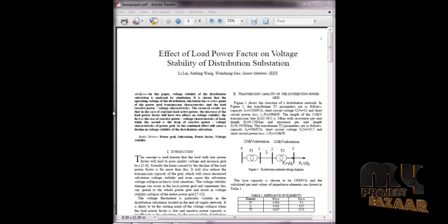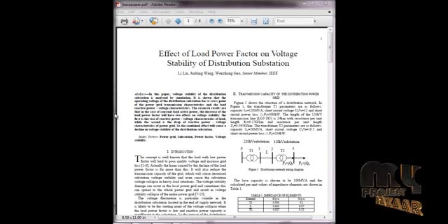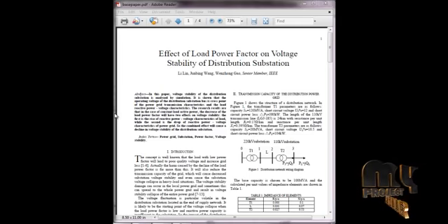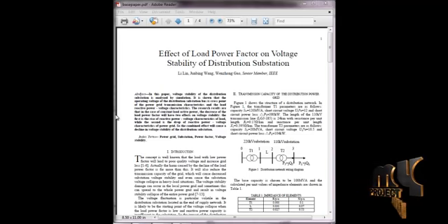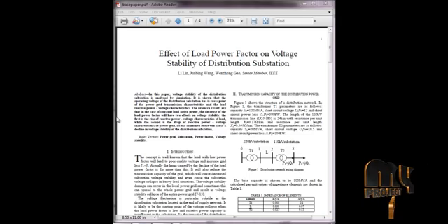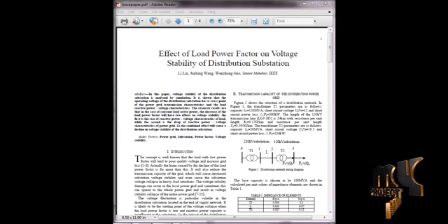Voltage and reactive power control involves proper coordination among the available voltage and reactive power control equipment. Many distribution network operators operate such equipment locally by using conventional controllers to maintain the voltage in the distribution system within the acceptable range and minimum power loss. Different methods have been proposed to improve the voltage and reactive power control in distribution systems, both in planning and in the operation stage. In our paper, we use DVR to stabilize the voltage in the substation.